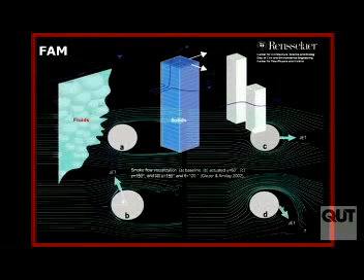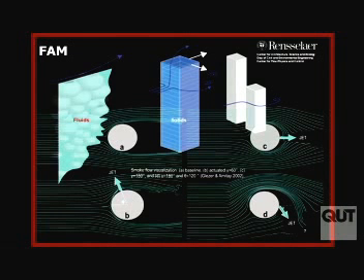If I look at fluidic aerodynamic modification, that's changing the flow, so how am I going to change the flow around a structure to improve its aerodynamic performance? And the way to do that is clearly to inject flow somehow. So you can see here various ways of, if I inject flow, I change the flow around the structure, and by doing that I change the pressures, and I also change now the loadings on the structures. Some of you will have played cricket and you will have spun a ball. That is not unlike injecting fluid to the side of a structure, and you're creating now a lateral force, and of course in a cricket ball that causes it to curve. So by a Magnus type effect, I'm changing the flow. There I'm spinning the ball. If I could inject flow behind the structure, then I can change the flow around the structure and hence its aerodynamic performance.